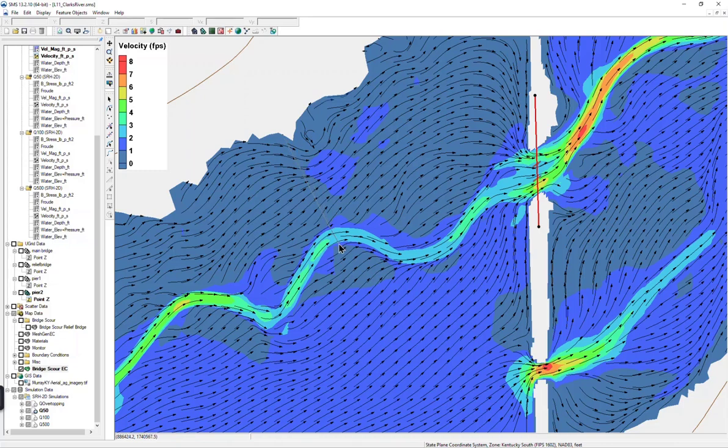You can have multiple points, and generally it's best to draw this perpendicular to the flow, but it's not absolutely necessary because the flow direction is taken into account in the computations. And then extend the arc across the entire width of flow that's tributary to that bridge. Double click that to end it.